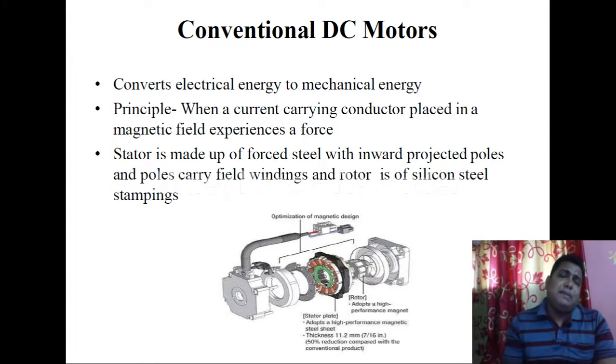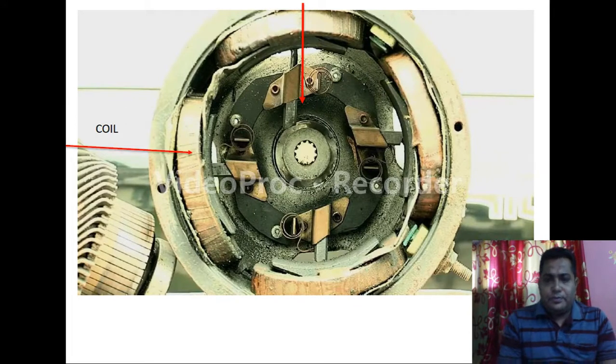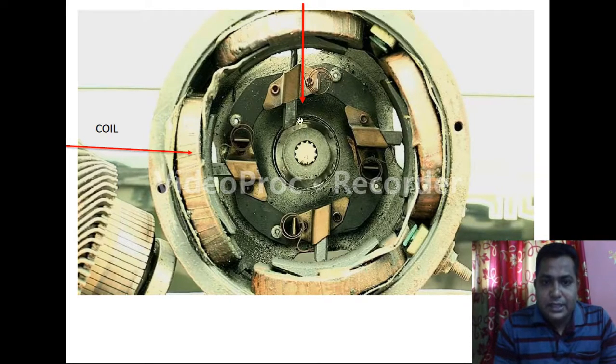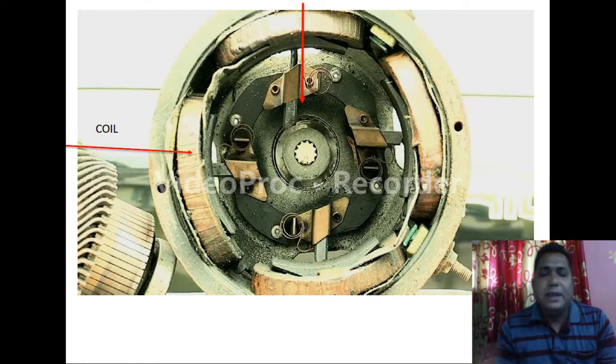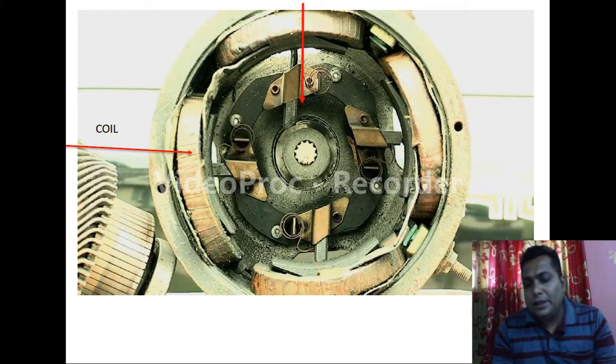Nowadays these applications are reducing. Instead of DC motors, three-phase induction motors are taking the market. As you can see, there is a very interesting diagram, so follow my pointer. These are the brushes. This outer section is the commutator, and the brushes are connected with it. The brushes collect whatever current is flowing, and make it unidirectional, so that the output may be DC.